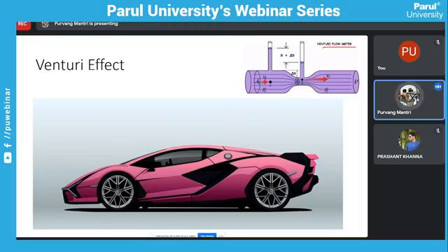As we took the example of the hose pipe for cleaning our vehicle, where we pinch the hose pipe, similarly here in the venturi meter, in the converging area the cross section area of the pipe reduces till the throat. The smaller cross section area is constant in the throat region, and in the third part the cross section area increases gradually.